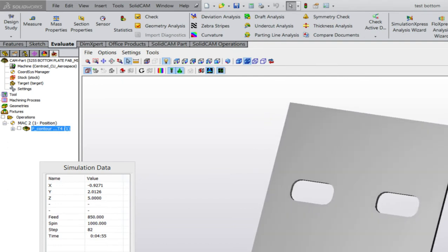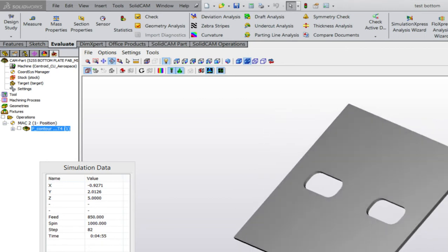Is the extra amount of time you would take with a smaller end mill worth it? Would it be worth it to cut with a big end mill and then change the tool and put a small one in there? Yeah, that's common. You wouldn't do it here because it's such a small pocket. But what if this thing was 10 by 6 inches? You might come in and hog all that material out with a nice big end mill, like a 3/4 inch end mill, and then just run around the outsides with the small end mill to take out this little fillet. Yeah, that's real common. Yep.